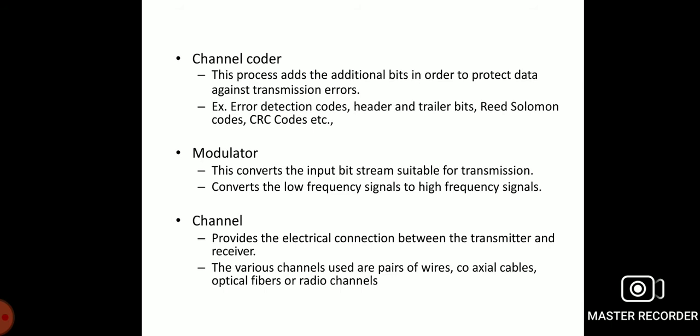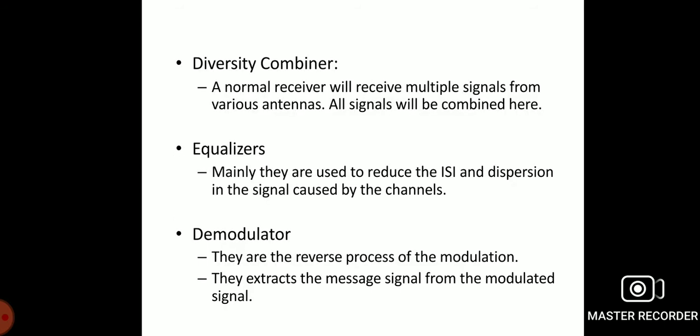The upconverter converts the analog filtered signal to a passband signal by mixing with a local oscillator signal. The low noise amplifier amplifies the signal so that the effect of noise on the signal to noise ratio can be reduced. At the receiver, the down converter is used to convert the received signal to baseband. Now the signal is received and available as an analog signal. The low pass filter eliminates the adjacent channel interference and noise.